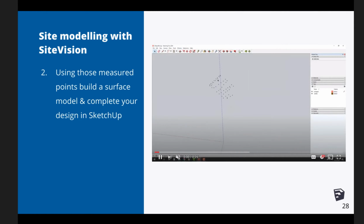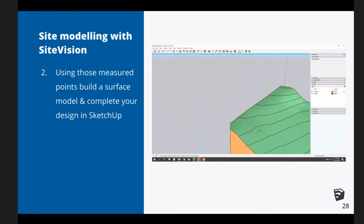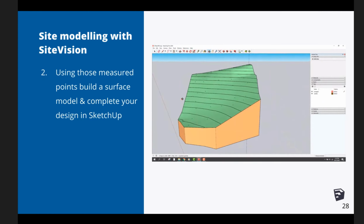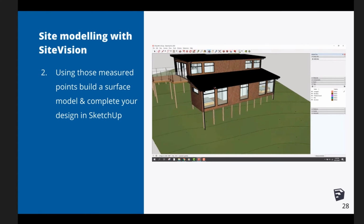You can then import these points in SketchUp and use them to create the surface model of your field. Over here, we have used the plugins of Point Gadget and Topo Shaper to do that, insert the points, and then create the surface of the field. And then you can add the house model, and you have a complete design.